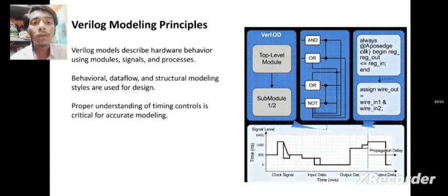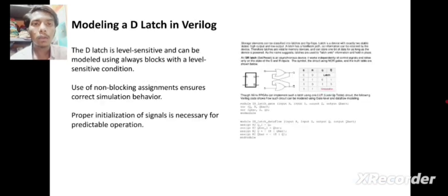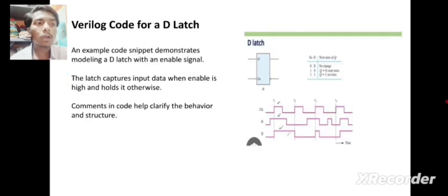The next is Verilog modeling principles. Verilog models describe the hardware behavior using modules, signals, and processes. The behavioral, data flow, and structural modeling styles are used for design. The proper understanding of timing controls is crucial for accurate modeling. The next is modeling a latch in Verilog.